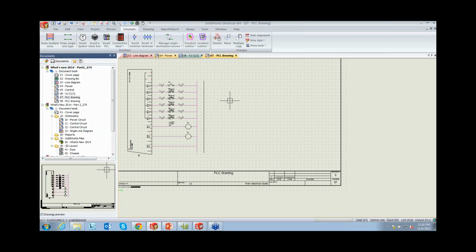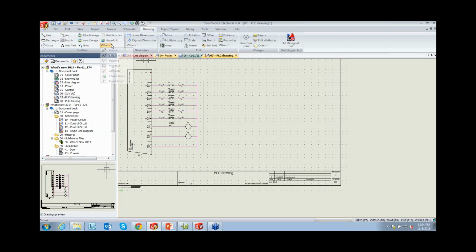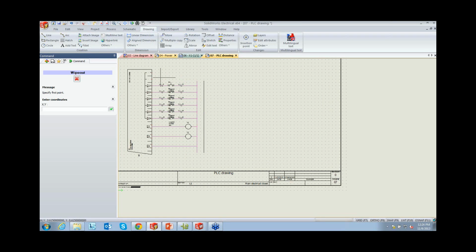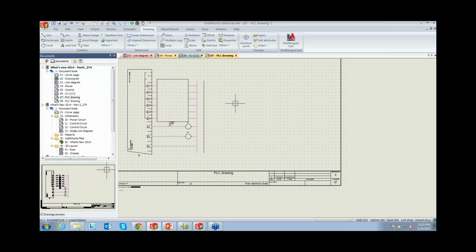And in the 2014 edition, they also added something called the wipeout feature. Now the wipeout feature, if you've got proprietary information or you're simply trying to hide some of your printable layers, it makes a big difference. Right, of course, and this is where it comes in, right? As in I've done it before, where I don't want to complicate the drawing too much. So I've hidden a few parts of the design, or you want to show it as a black box, but you still want to design it so that you can see what it is. So all the information that's in there still stays in there. It comes out with the report, your bill of materials, then you can simply remove that if you want to have two different representations of it.